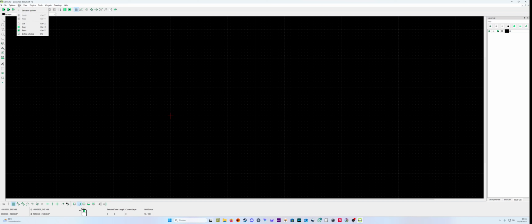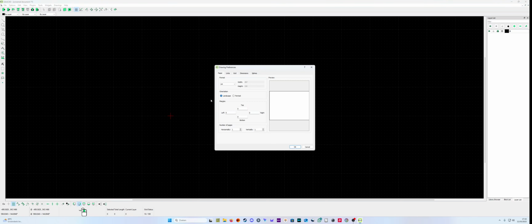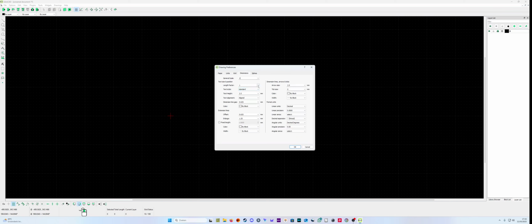We're gonna do some options. We're gonna go to the current drawing preference. We're looking for the paper size. That's A4, that's good. We do it in landscape, that's also good. So we got units, let's go to 0.02. And then the grid, auto, it's good. Dimensions, let's put this one on 2. So everything is at length factor 2. That means everything is a little bit bigger to read.